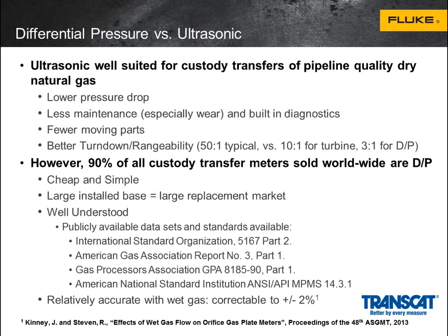So what are the various types of meters that are out there? Why differential pressure? Why not ultrasonic? Well, ultrasonic is very well suited for interstate and intrastate pipelines. High flow rates, you're covering a long distance, you don't want large pressure drops, you really don't want to have to shut the pipeline down to do maintenance. And obviously the fewer moving parts you have, the less likely it is that the unit will fail. The other thing that's really nice about them is they have wonderful turn-down characteristics.